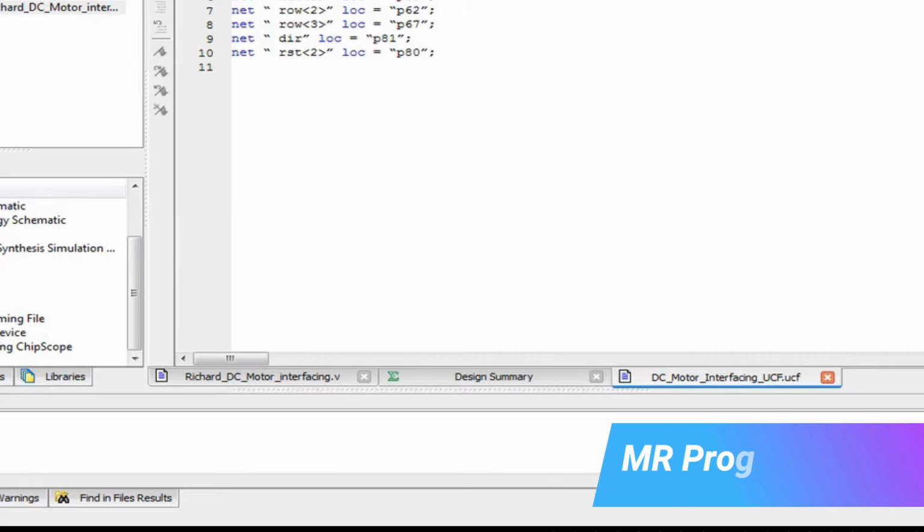And with this code we'll be able to communicate with your FPGA, just like how I have shown you these pins. Your user constraint file has pins, so this code will get connected to those pins, and accordingly it starts getting executed. What we are trying to do here is send the information from our program to a few interfacing kits, sending information from the computer. So your computer should have a USB connection where you transfer information through a USB cable to a USB programmer. So the USB programmer stays in between your computer and your FPGA kit.